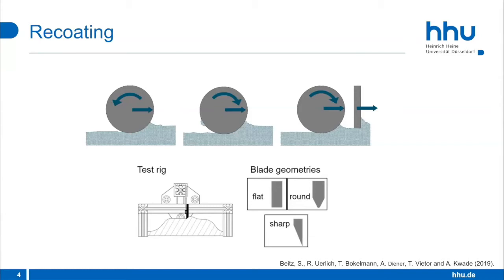So Johanna Peters from Evonik was just talking about the voxeljet machine, and if I got it correctly, I think they are using a counter or co-rotating roller, where you add the powder either directly on the surface of the previously printed layer, or as I said before, you move up the powder reservoir and then you scrape it over, you recoat it with such a roller system. And there are no general rules on which system is superior.